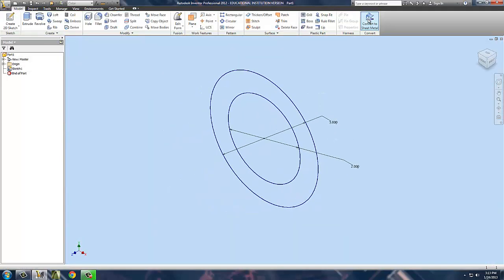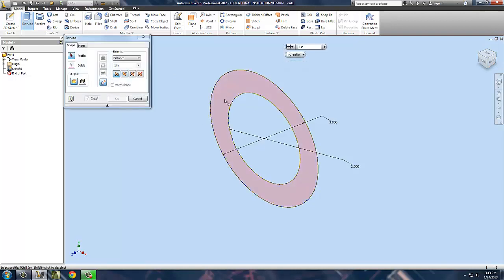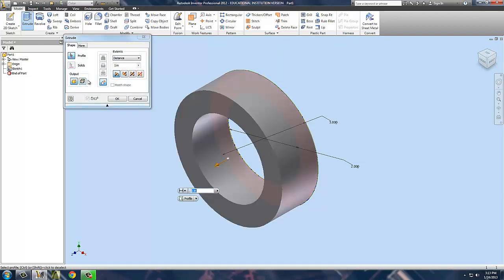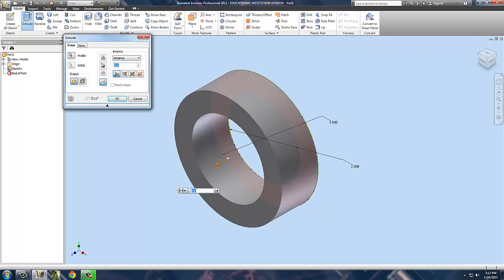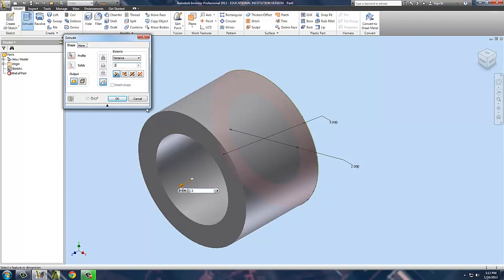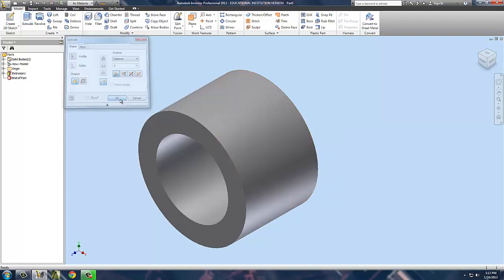So I'm going to finish this sketch and I'm going to model it a little bit so you can see what happens here. Notice our navigator bar tilts to what is effectively an isometric view with the front, the top, and the right side. I'm going to use an extrude command right now to extrude this profile I've now highlighted in pink to a given dimension. Now, we have our floating palette here. We have our traditional pop-up menu here. I actually don't need the pop-up menu, and most people don't. We can control almost everything we need from the floating palette, but we're going to use the pop-up for this purpose right now. I'm simply going to make this thing a 2-inch pipe that has a roughly 1-inch thick wall, and go, okay, there he is.